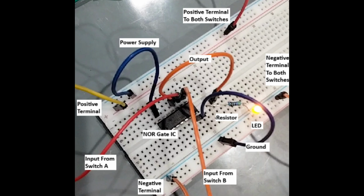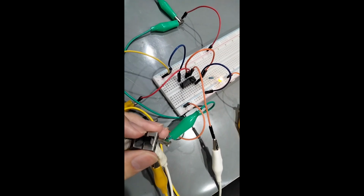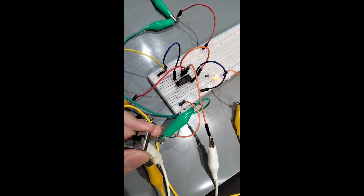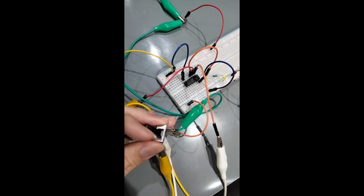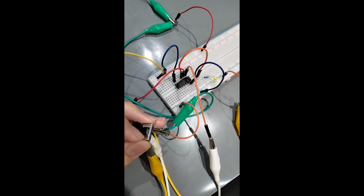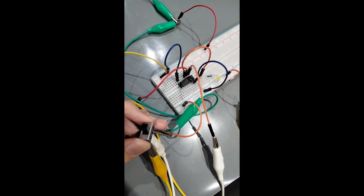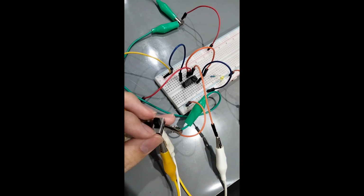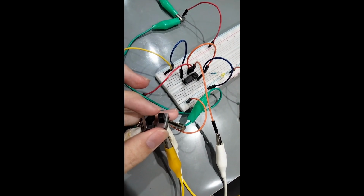Now this is the NOR gate, which does the exact opposite of an OR gate. It also has two inputs and one output. Currently it's 0, 0, so the output is 1 as shown in the LED. Now it's 1, 0, it will become 0, and 0, 1, it will also become 0. Then when you switch it to 1, 1, it will become 0.